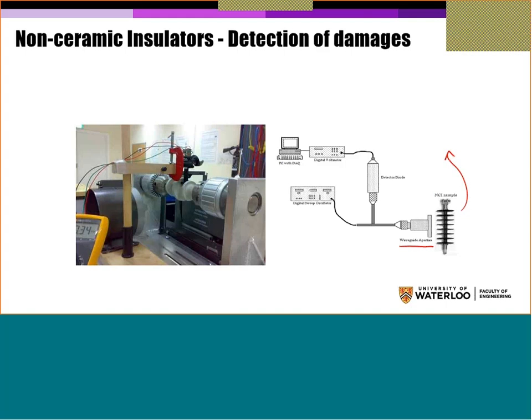For example, you have here three different types of material. You will have the insulation, meaning rubber and fiberglass, if it's healthy, and the dielectric constant here is about 3 to 5. Then if you have an air void or crack, this is 1. If you have metallic, this is very high, in the thousands. So based on the dielectric constant, the amount of reflected wave will be different. This is the principle that we use to detect.